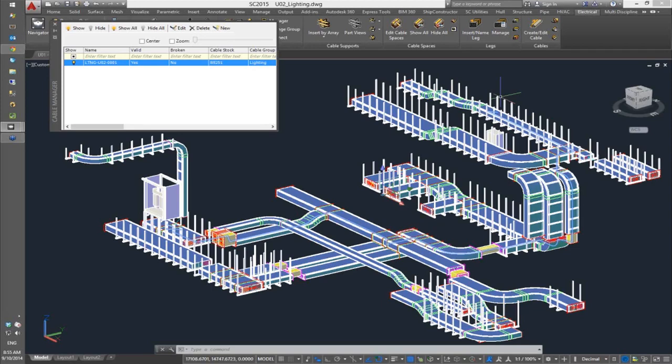The question here is, is there a way to know when the cable tray is full? Yes. There are 2 ways of doing this. You can monitor this in the drawing, either the cable drawing or in the wireway drawing. There's a show cable fill, and as I said, the cable spaces are the means for monitoring the cable fill. I can only do that if I have a space allocation that has cable spaces defined in it. If not, I can't monitor the space in that space allocation.